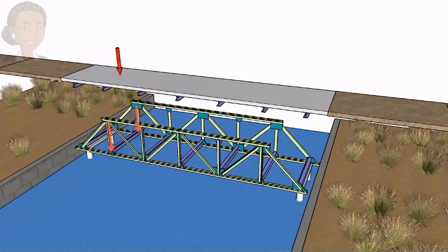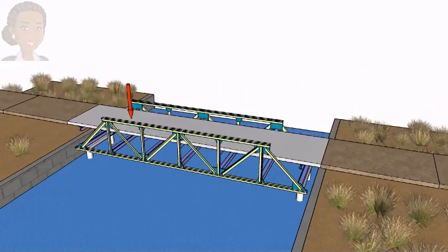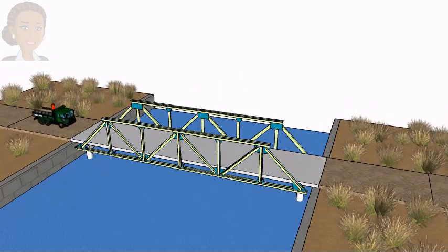So, as the truck moves forward, this pattern of load transfer shifts forward from joint to joint until the vehicle leaves the bridge. We use this moving load pattern to construct the influence line for a truss member. However, in drawing the influence line, we only need to consider the loading cases in which the load is directly on top of a beam. All the in-between cases would be automatically captured by the straight lines that we draw when constructing the influence line.